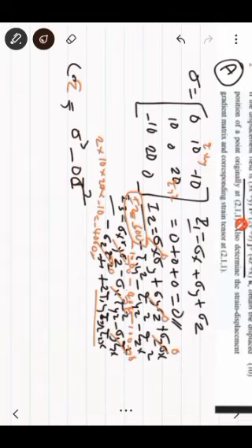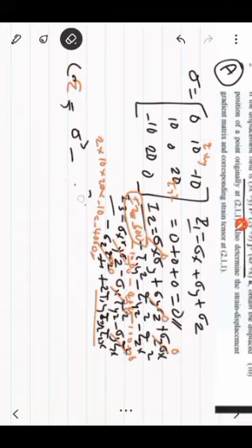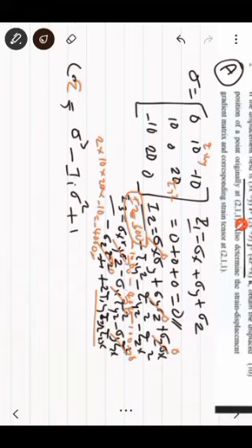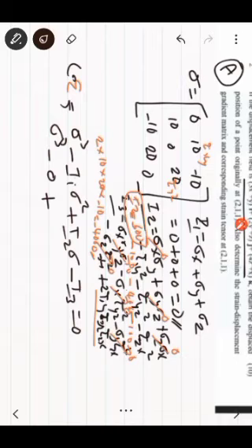First I write the equation, then we solve this: sigma cube minus I1 sigma square plus I2 sigma minus I3 equal to 0. Substitute all I1, I2, I3. Sigma cube minus 0, plus I2 is minus 600, so you get minus 600 sigma. I3 is minus 4000, minus of minus, you get plus 4000 equal to 0.